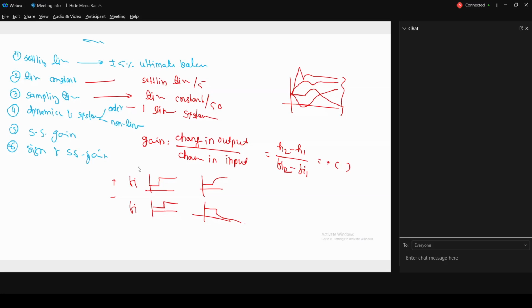It's very easy to change flow rates, but changing concentration so often is not possible. Then even if the rest of the parameters are favorable for concentration, we may not go with concentration as the manipulated variable unless we have no choice. But if there is a flow rate where some of the parameters I explained might not favor it, still we will go with the flow rate. So considering all this, we will be in a position to select the proper manipulated variable.